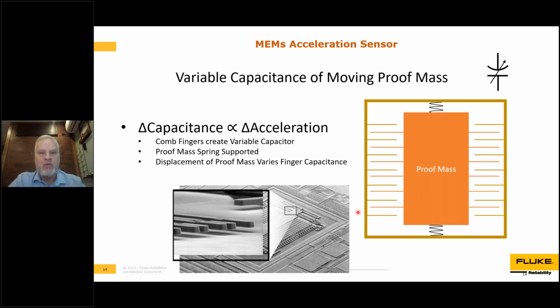Most of your cell phones will use this style of accelerometer to measure the movement of your phone. Everybody's used to that. They're very low resolution compared to what we use in this industry, but nonetheless, they have some of the same characteristics, but keeping in mind that you can measure actual gravity. In other words, this sensor can be aware of which of the 3 accelerometers is pointing in the direction of gravity and measure gravity because of that. That's what gives these that characteristic low frequency response that everybody talks about. So that's the big advantage of these sensors.